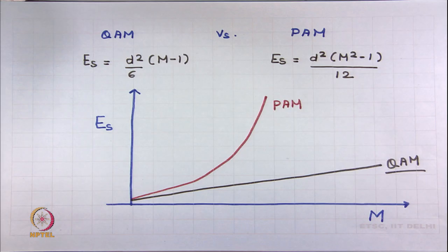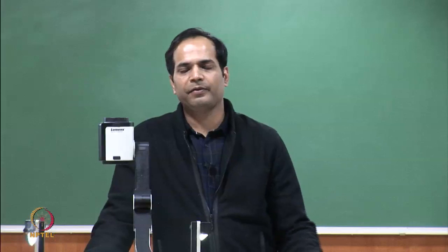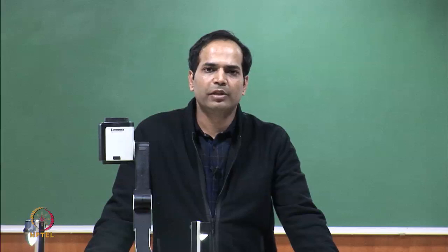Okay. And we looked into another modulation scheme, which is the quadrature amplitude modulation scheme, and there we have seen that you use the complex dimension. So, you can have complex signals, and once you allow complex signals and use quadrature amplitude modulation, the one straight away advantage is that you reduce the bandwidth inflation that happens when you do this baseband to passband conversion.